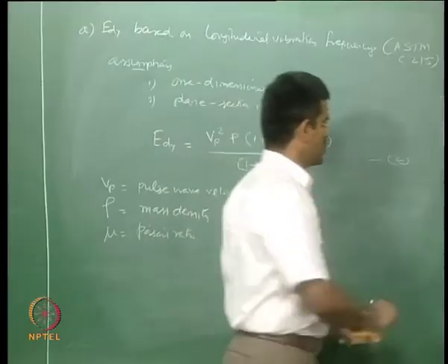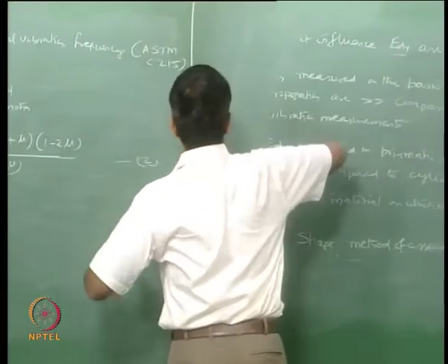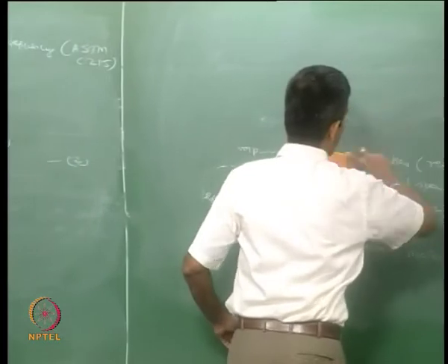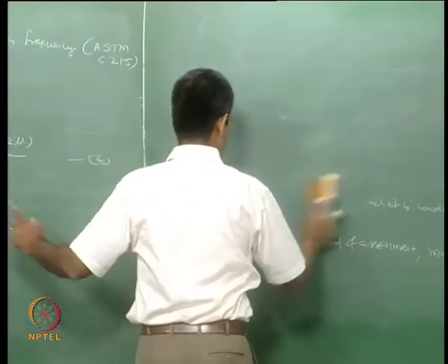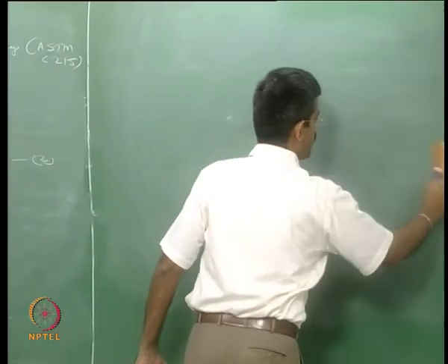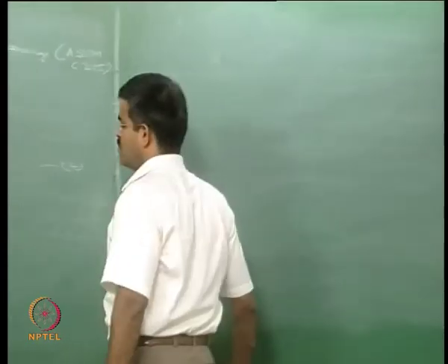So, using this equation I can find out dynamic modulus of elasticity if I know the pulse wave velocities.